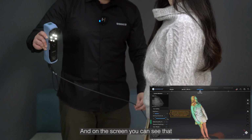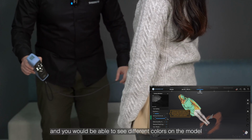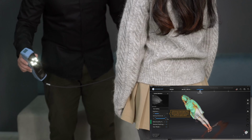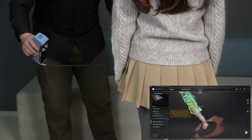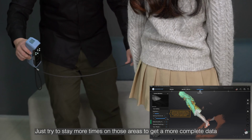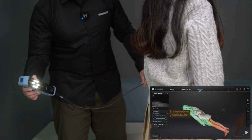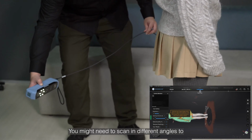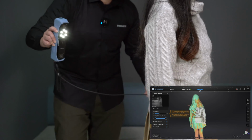And on the screen, you can see that we opened the data quality indicator, and you would be able to see different colors on the model. Try to get them green, but if you cannot, just try to stay more times on those areas to get more complete data. You might need to scan in different angles to have more thorough data.